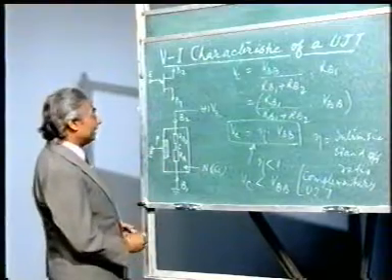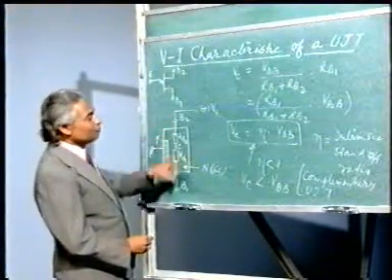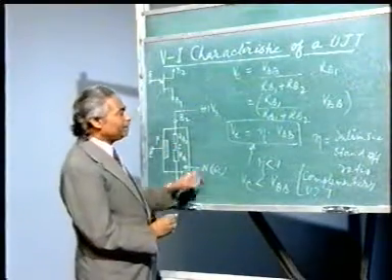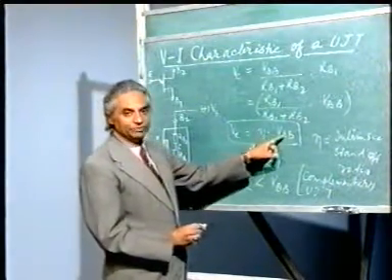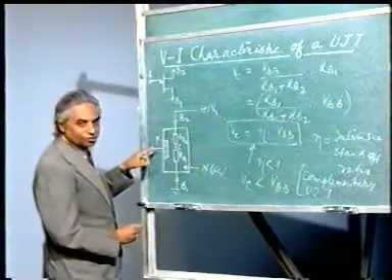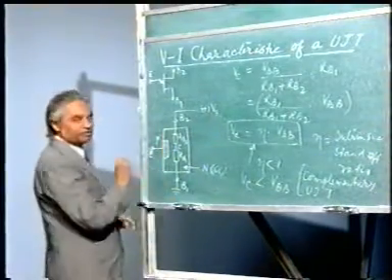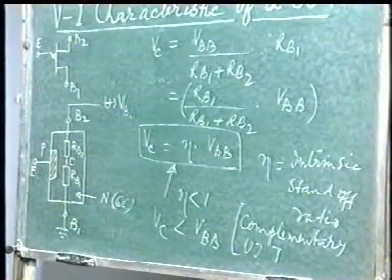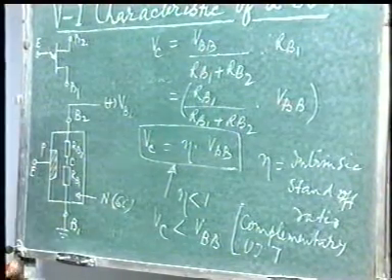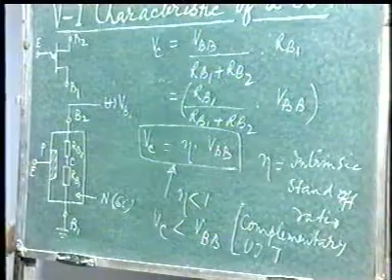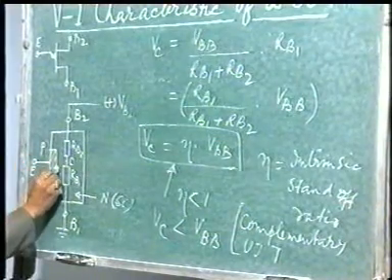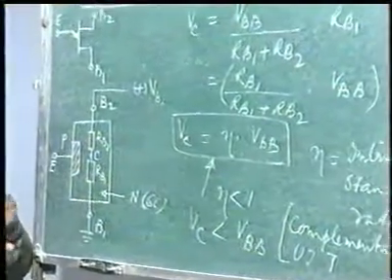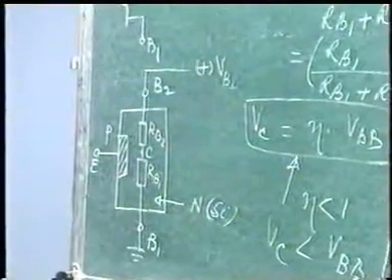Now what is happening when I am giving this supply? You see the potential Vc will be obtained here, and that will be given by this equation, and it will depend on VBB. It will also depend on spacing of the two, and it will also depend on the construction of the device. Now suppose I give a supply separately at this point emitter from external supply. What will happen? You see this is P type material, this is N type material, and this is a junction. So what type of junction it is? It is nothing but a PN junction, and that is nothing but a diode.